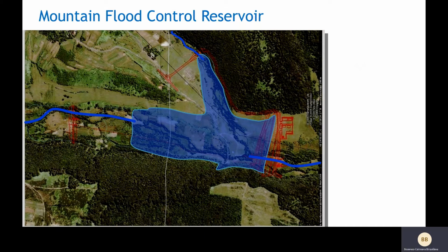This change of the level may reduce the upstream dam slope stability. Assessment of the slope stability under transient condition is an urgent task that will ensure the reliability of flood protection. This problem can be solved by simulating transient seepage by means of the finite element method.